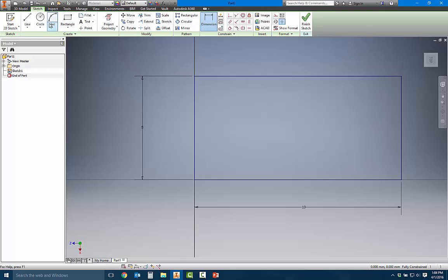So the first thing I'm going to do is pick this circle object, and I'm going to drop it out here. See, it's already doing really cool stuff for me. Like it gives me suggestions on where the middle line is. So there's one there. You can see it's at the -5 millimeter mark on Y. And this one, you can see it's doing the same thing over here. It's doing 2.5 on that side. So I'm going to start mine out here somewhere. I'm going to run up to that part.